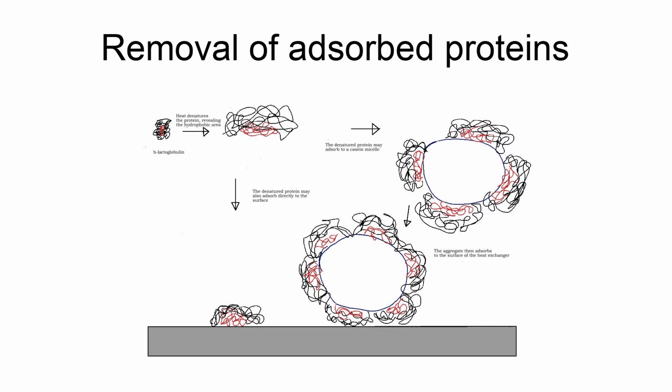Generally speaking, highly alkaline cleaners with peptizing and wetting agents are most effective in protein removal on food contact surfaces. Cleaning temperature is also a concern for effective protein removal. As temperature increases, the activity of the cleaning compound increases, making soil removal easier. However, at higher temperatures, around 55 degrees Celsius, proteins denature and cleaning efficacy is reduced. Alkaline cleaners are classified as compounds with pH 7 to 14. Proteins are most effectively removed from surfaces by cleaners with a pH of 11 or higher.